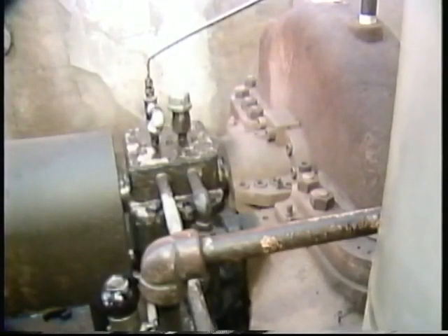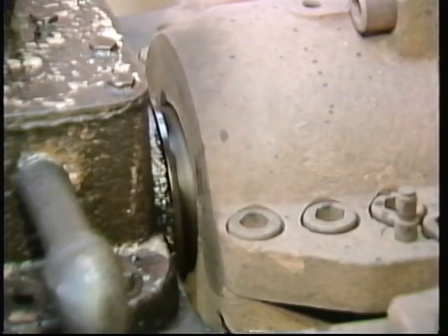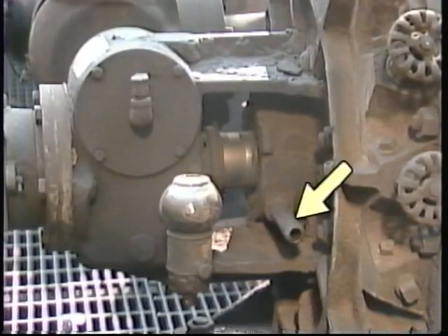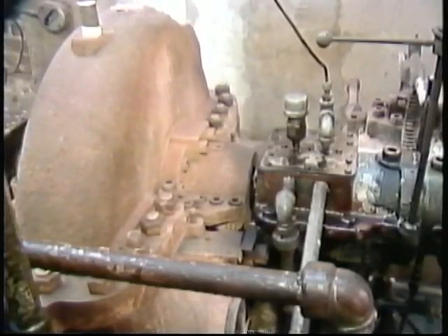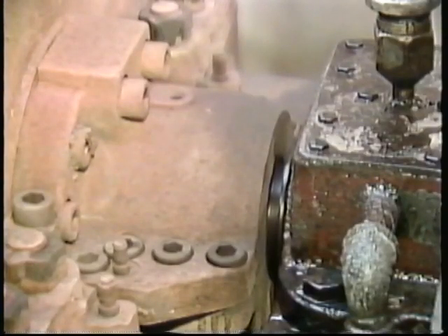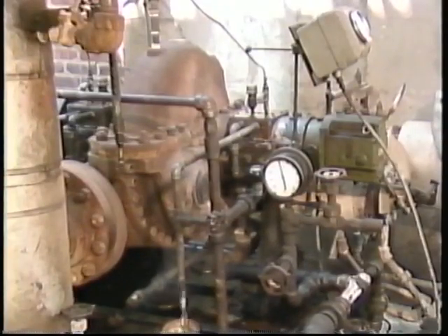Besides draining the turbine and preparing the lubrication system and the cooling water system, you also need to make sure that the seal system is in working order. Any leak-off vents for the seal system should be clear and open. While the turbine is warming up, look at the turbine shaft where it penetrates the casing. If the seal system is okay, there shouldn't be an excessive amount of steam leaking past the shaft to the atmosphere at these locations.